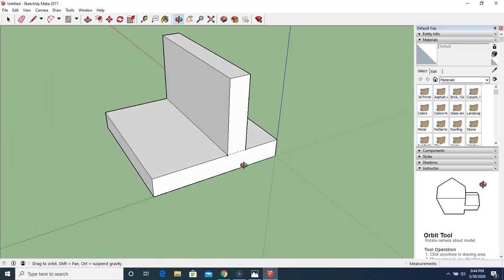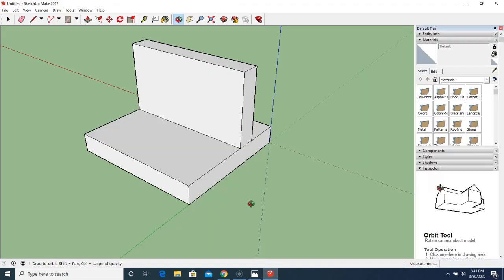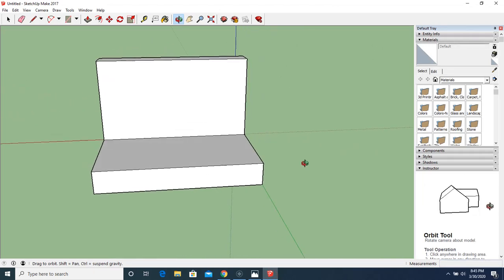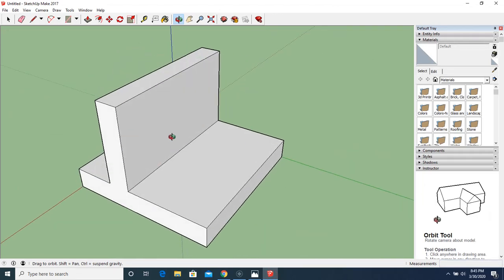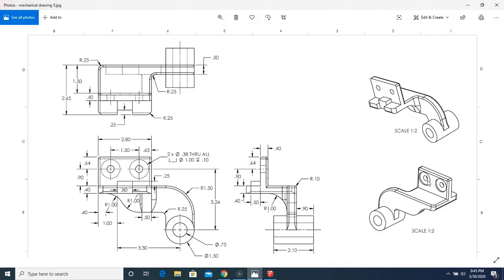Now, to avoid making the mistake of putting the counterbored large holes on the wrong side, let's make sure we swing this thing over, and we're going to do the layout from here. That's a common mistake, is to put the counterbore, which is this indentation, on the wrong side.